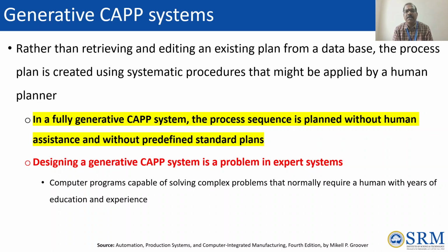If not, and a similar plan is there, where a few features are different from the standard process plan available in our database, then we retrieve the standard process plan and see what changes are needed for the product features. Accordingly, we change the manufacturing process or assign machine tools, resources, human operators and tools. Then we modify the standard process plan and store it again in the database for future reference for other orders. Once we have that, we can proceed to production.